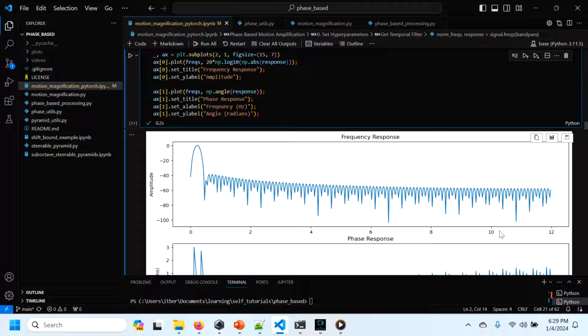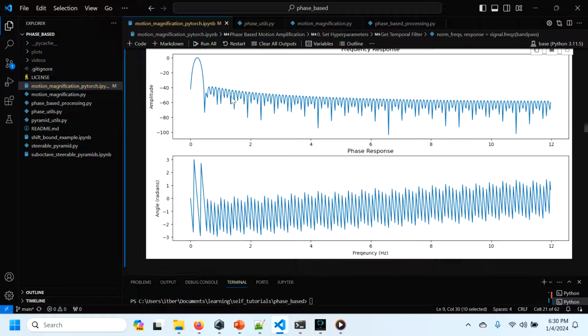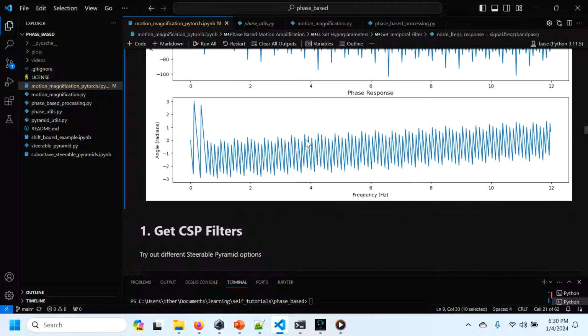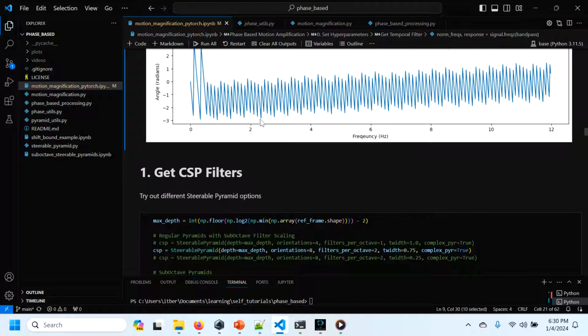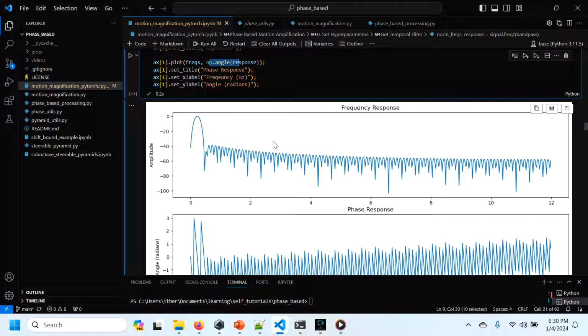So like I said, the Nyquist frequency is 12, so we're going from 0 to 12. And I have the magnitude and phase response. You can see right here we're roughly at about 0.2 to 0.25 in this lobe right here, and we have a pretty nice roll off. We're about 40 dB down from the peak, which is pretty good, and we kind of roll off to about 60 down as we go far off. So it's a pretty good response, which is what we wanted. And we can also use a Butterworth right here, which is going to have a more flat response than this FIR filter.